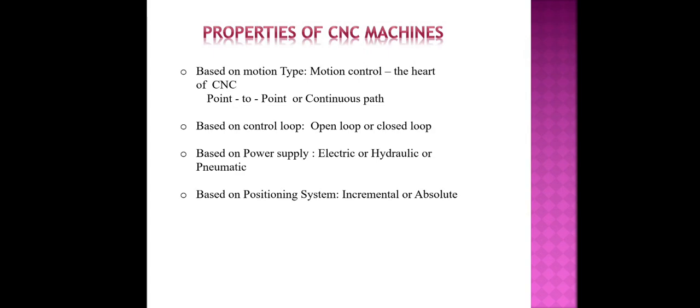And the motion type, contouring system. It is used in CNC machine tools such as milling machines. These machines require simultaneously controlled axes. Contouring machines can also be used as point-to-point machines, but it will be uneconomical to use them unless the workpieces also require contouring operations to be performed on them.